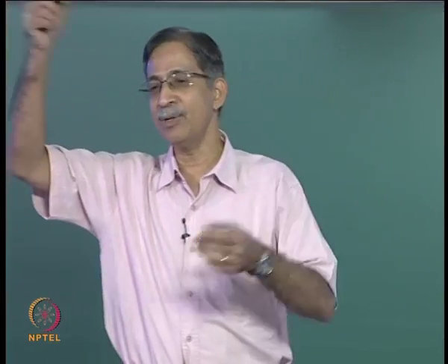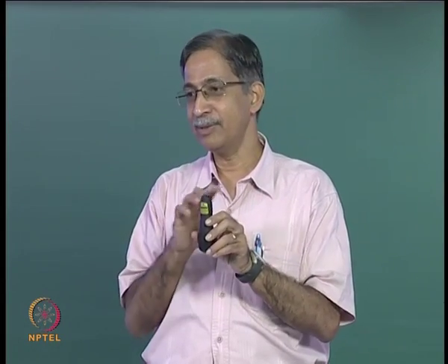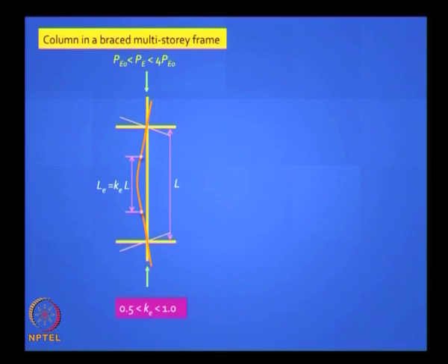If both ends are pinned, it is unstable, okay. So that is the other. Let us say you have a beam, you have a multi-storied building in a column, and the column has pinned ends, that means the beams have 0 stiffness. Then that is asking for trouble because it is going to sway like hell, it will be unstable, okay. So to show you a picture of a column in a building, you need some elements in the building which will give the bracing effect. So it usually comes when you give some shear walls, etc. So the building as a whole is prevented from swaying, so every column in that building will become braced, okay.